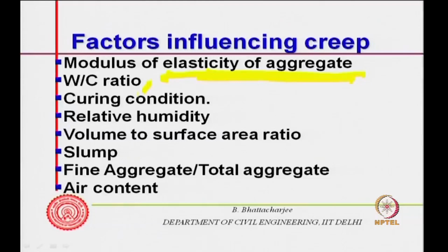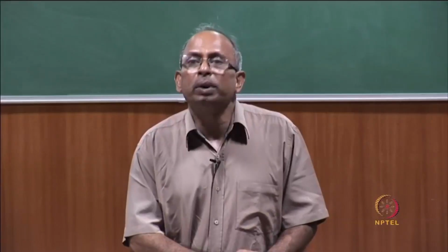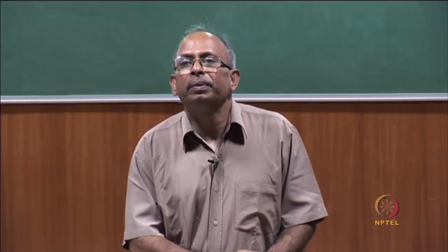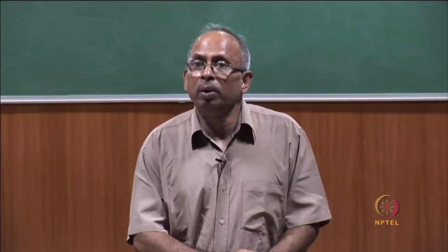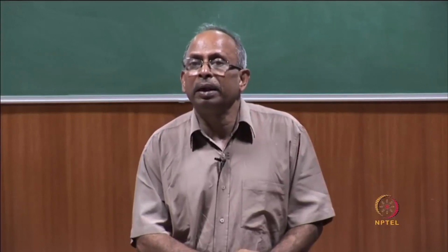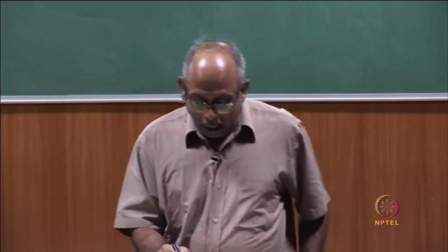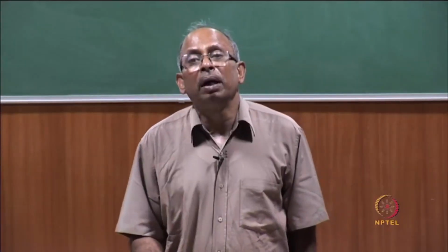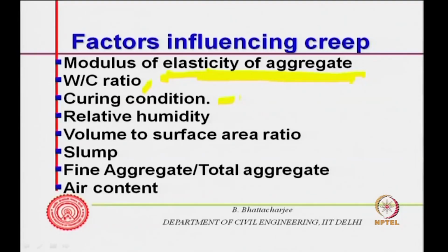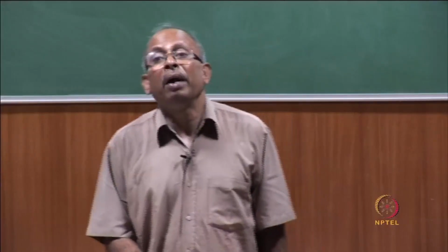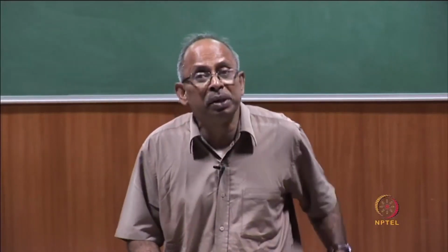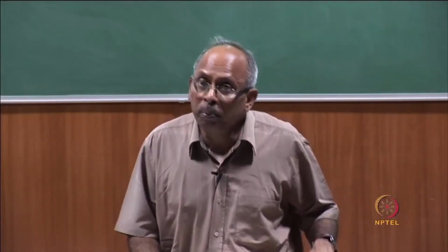Water cement ratio essentially governs the porosity and pore structure of cement-based material, and therefore water cement ratio is also a factor that influences creep. Curing condition, the environmental condition, whether it is fully saturated or what it is, matters, because finally it is water movement. Therefore curing condition is a factor, and it is also a complex interaction with the hydration process, which continues over a long period of time.